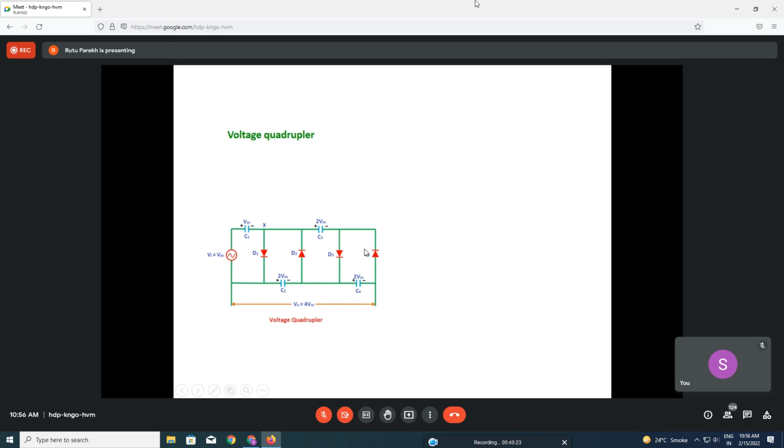So here also now you can understand how the things are connected, right? So that's the beauty here, the way the diodes are connected. So here, during the second positive half cycle, right? So this will be charged. So if you go on adding more, then it will be 2 VM. So now we are adding one more, D4 and C4. Okay, and the polarity is this polarity and this. So the alternate connections are like that, and we are taking the output across this.